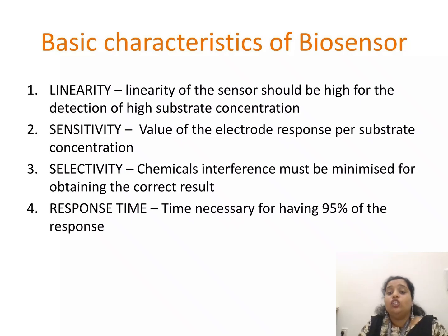Then comes selectivity. So chemical interference must be minimized for obtaining the correct result. That means whatever bioanalyte you want to test should only get detected, rather than other elements which might also be present in the environment. Then response time is equally important. It is the time necessary for 95% response. Okay, it's not that you keep the biosensor and some of the time it gives a response, the other time it does not. So at minimum, 95% of responses should be recorded. And again, speed of response: it should not take a long time to give you the result.